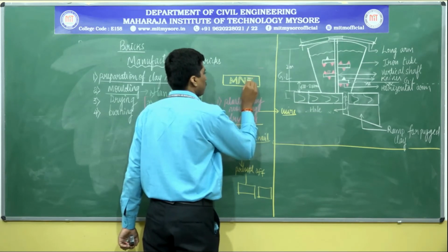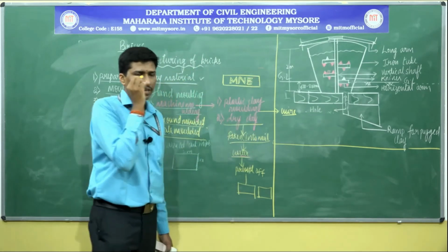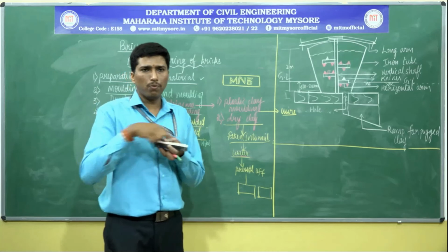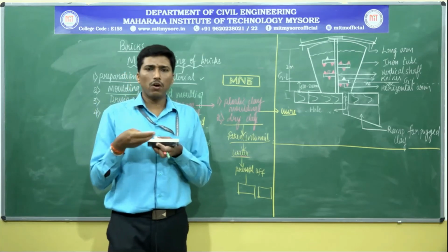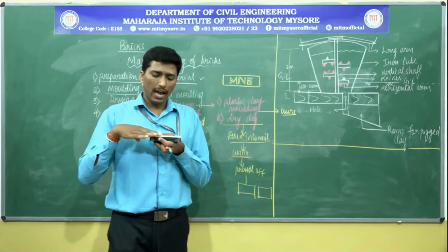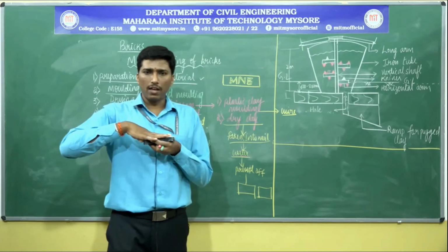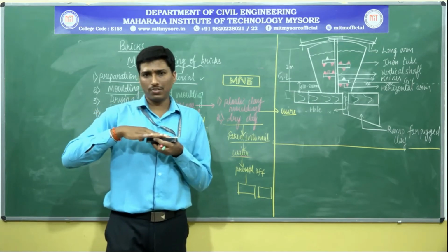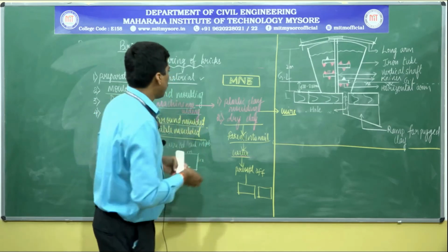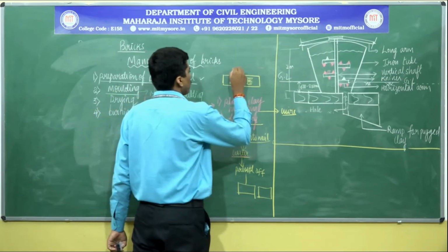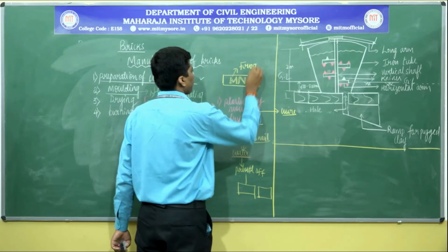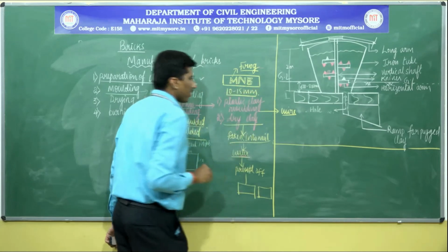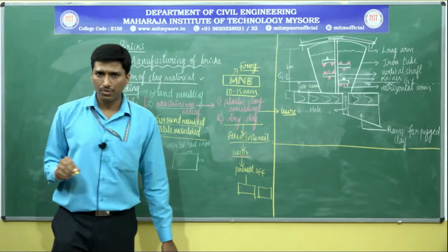The purpose of the frog is to reveal the manufacturer's identity, a trademark on this. Another thing is that it is laid in the top portion. When it is laid on the top portion, it acts as a medium for covering or mortaring when another brick is placed over it. Hence, these kinds of protrusions we call a frog, which may range from 10 to 15 mm.